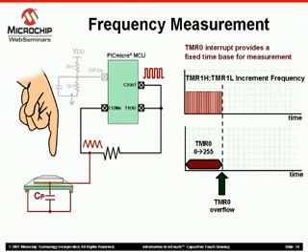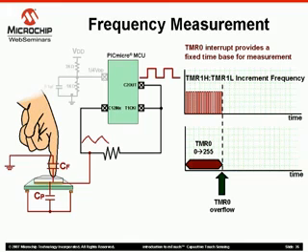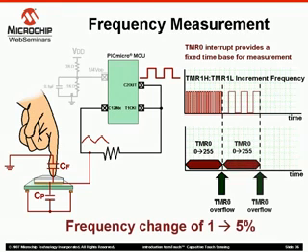Capacitance created by the pad alone results in a corresponding square wave frequency. On a timer 0 interrupt, we read the current count value in the timer 1 registers and store it for later reference. Once a finger touch is introduced, the sensor capacitance increases. This increases the RC time constant, effectively decreasing the frequency of our square wave output. Therefore, on the next timer 0 interrupt, when we read the contents of the timer 1 registers, we should get a smaller value than the previous interrupt.